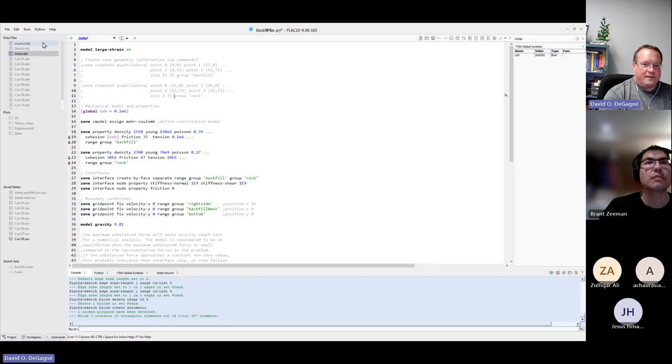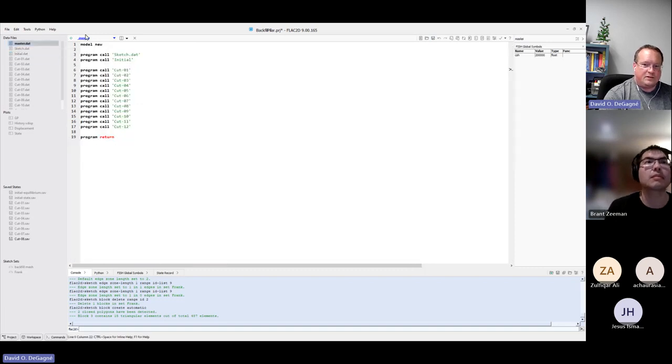And then you just go back to the master file and run this from beginning to end, because this is really the end state that we're interested in when it's fully exposed. And then keep track of the displacement histories, if they're starting to plateau, or if they're just running out forever. If we're getting meters of displacement, then that's really an indicator that it's not strong enough, it's not stable. There is a solution. So at a certain point, you should have a fully stable system.